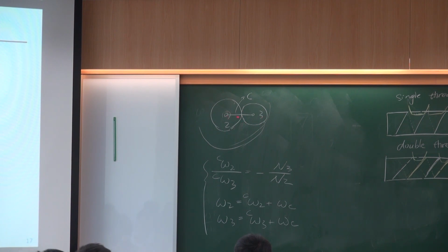If we are considering the crank as a fixed bar, then the relative speed of 2 to c and 3 to c, they are just the gear ratio, the ratio between the number of teeth. It's similar to regular external gears, when we consider c as a reference. Because right now c can move, so it's a bit different from our previous external gears.